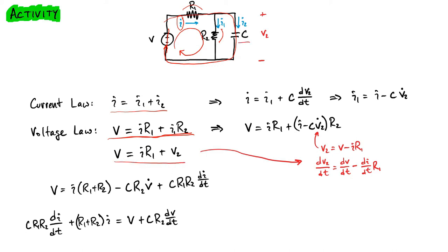And so we could decide to go ahead and plug in for V2, but remember, in this case, V2 is harder to use because our circuit relationship for the capacitor is that I2 is equal to C times dV2/dt. So it's difficult to substitute in here for V2 using this equation because in this equation, V2 appears as a derivative. So let's hold off on that and wait.